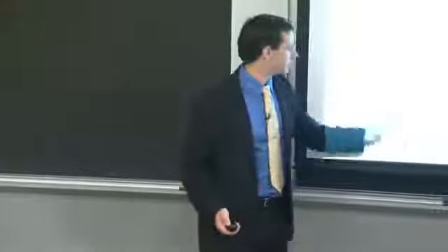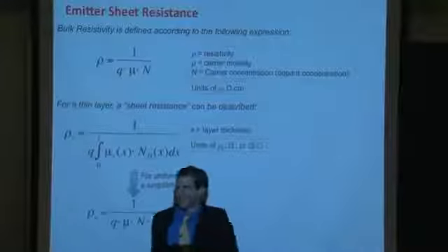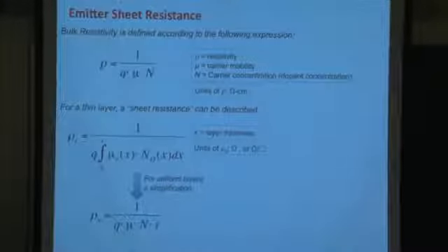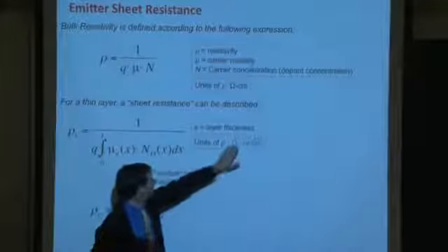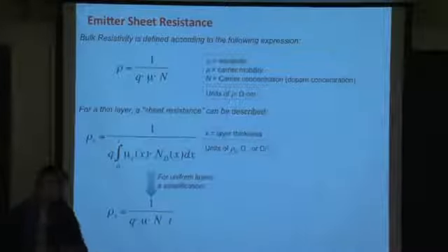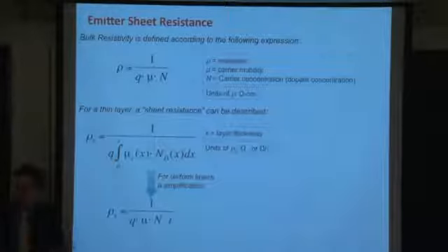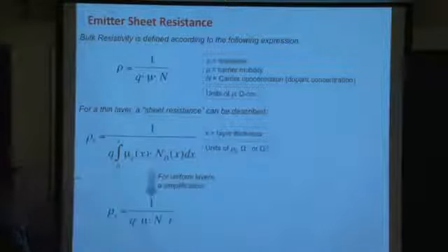So let's keep this thought for a minute, and let's now try to calculate the total power loss due to the emitter sheet resistance, because now we have this weird unit of ohms per square. In reality, it's ohms, but when we think about emitter sheet resistance, we're thinking about a square of the material. We have units of ohms per square being a unitless parameter. So, resistivity had units of ohm centimeter. We divided our resistivity by our thickness of that emitter region, so our units became ohms. Right? And ohms per square here is the units typically given for emitter sheet resistance.